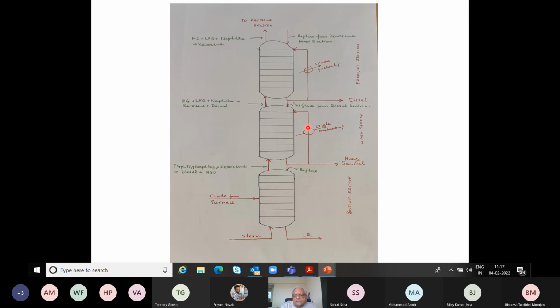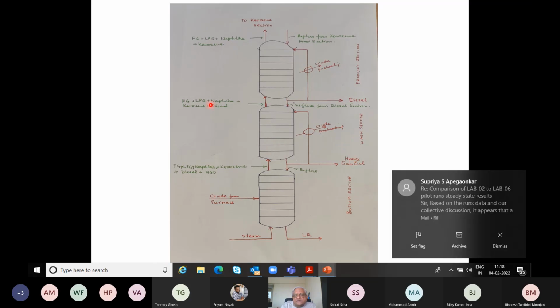The heat withdrawn here is taken into the crude preheat train, and in this case it might be in the hot preheat train. So this cools and condenses the diesel fraction which is trying to go up. All the diesel range components going up here get condensed, and they travel down, and that's where we withdraw it. Beyond this particular column, you now have vapor, which is everything other than these two fractions, heavy gas oil, and it has everything else, including diesel.